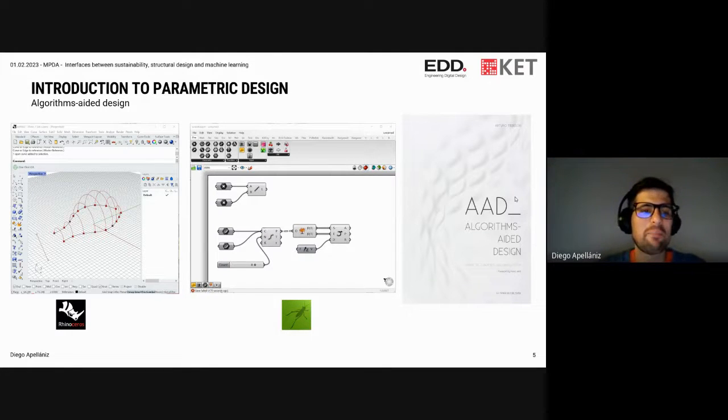In this slide, I'm showing the interface of Rhinoceros on the left side. Rhino is a 3D modeling program, and there is a plugin for Rhino which is Grasshopper, and Grasshopper is basically a visual programming environment in which we can create algorithms by connecting these boxes or components, and with these algorithms we automate tasks in Rhino, such as the creation of these relatively simple geometry objects that you see on the left side.